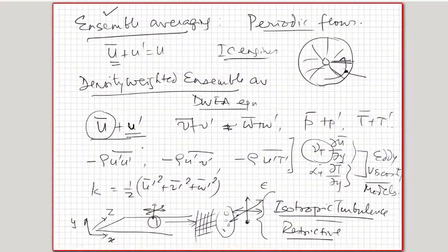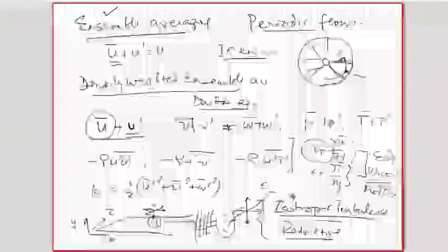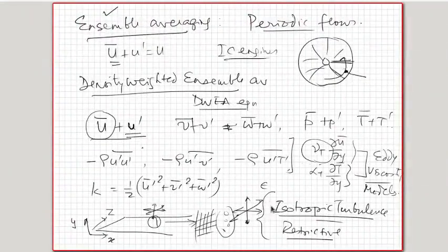So in engineering, we apply these Eddy viscosity models for all kinds of flows, isotropic as well as non-isotropic turbulence, and they seem to be giving reasonably acceptable results for engineers, but for a purist person on turbulence and fluid mechanics, these results are way far away from the correct results. But engineering is very tolerant to that kind of results, so we do accept it. So Eddy viscosity models are popularly used in engineering, although from the pure turbulence point of view, they are not supposed to be accurate models.